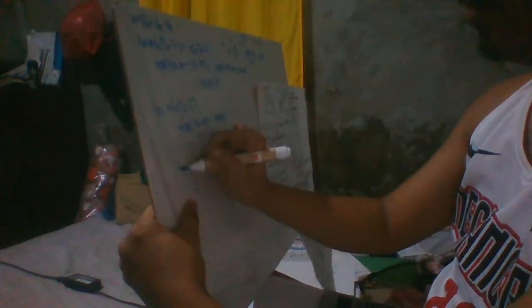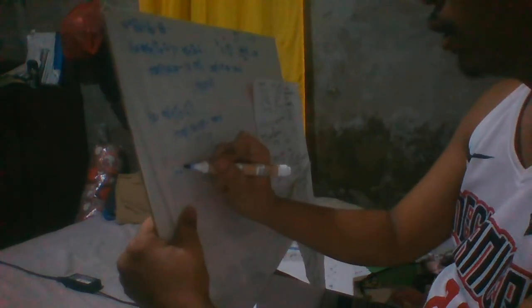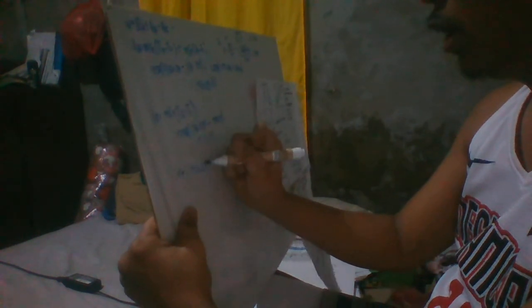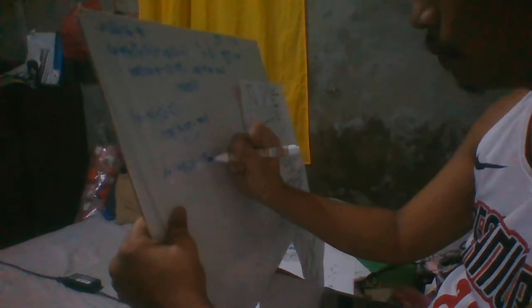As we go back to the equation, total work is equal to work added in constant volume and constant pressure minus the heat rejected. So 1,398.68 minus 595.09.